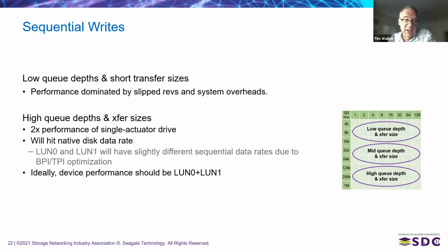That's average, and some head disk combinations delivered 270 and some 240. As you work your way across, you can see variations in sequential throughput. Since the two actuators have different heads and media, you can see different performance on the two actuators as well. But ideally, we expect to see the performance to be the sum of the two at any given place on the media.